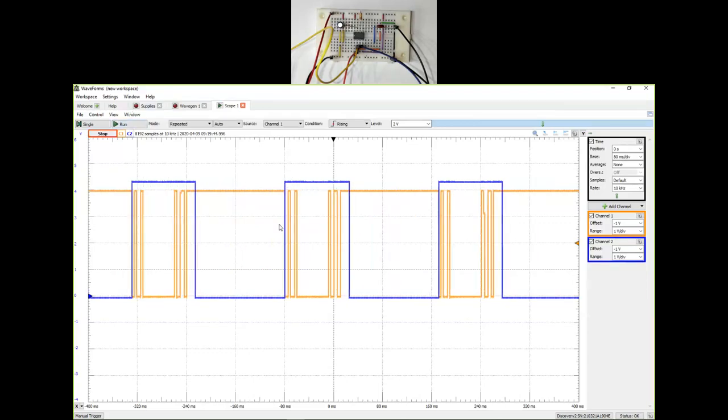Okay, so there were a couple of things that I forgot to do, and I was trying to see if things work or not. The two things were the power and ground. Once I did that, I was able to take a look at my fake switch data versus the output. So as you can see on this plot, the orange wire indicates the fake switch. I'm measuring that on pin 2, and pin 3 is a clean output because it's not allowing the capacitor to discharge very quickly, and it is going down just a little bit beyond where that bounces because we have used a capacitor of 1 microfarad.